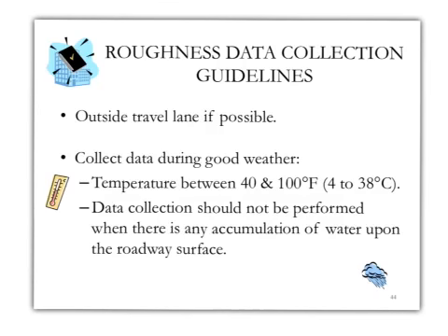Data collection also shouldn't be performed when there is any abrupt change in the weather. If there is a trend that the temperature at this time of the year is around 50 degrees, and that day in particular it was 32 or lower, then you wouldn't measure the roughness readings on that day.